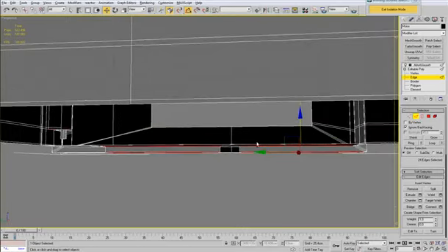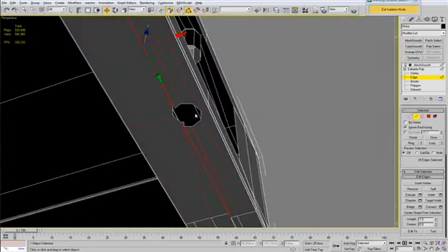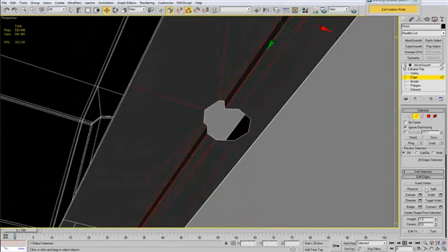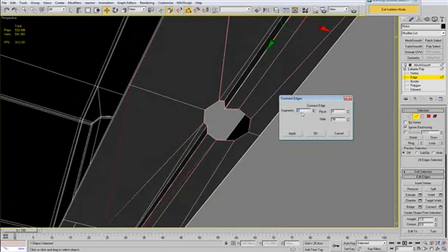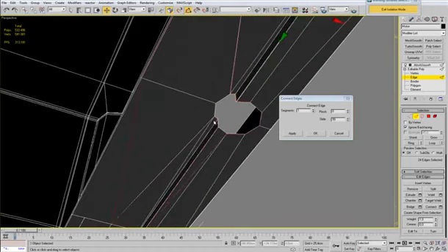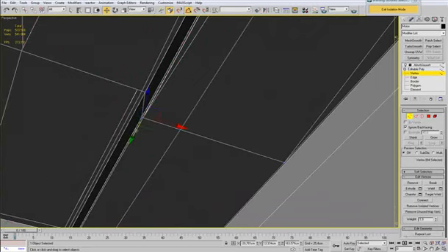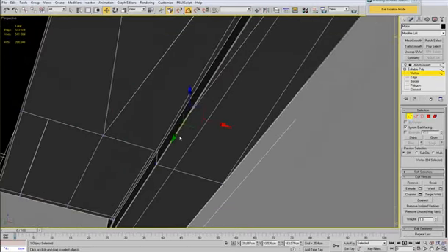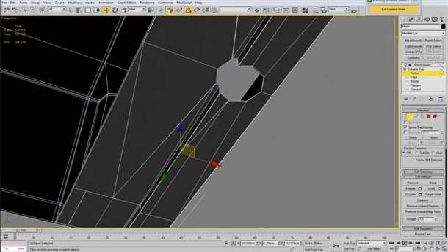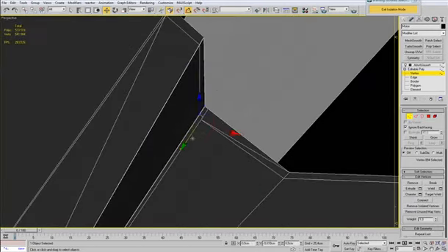Okay, deselect that one in the back, and now I can make the connection I need. Yeah, unfortunately it's not going to work properly, so I'll have to bring some of the vertices by hand using the edge constraint mode.